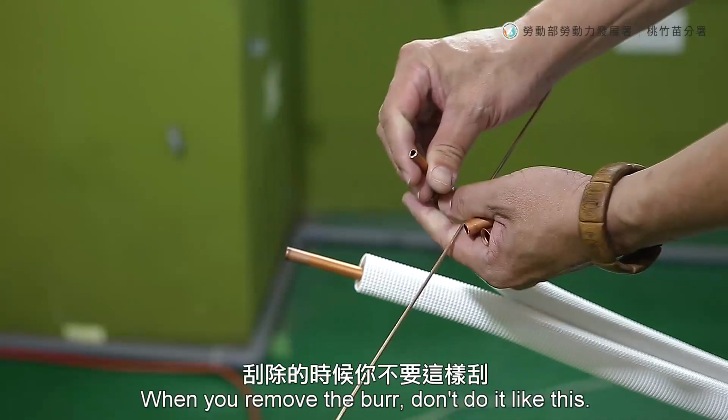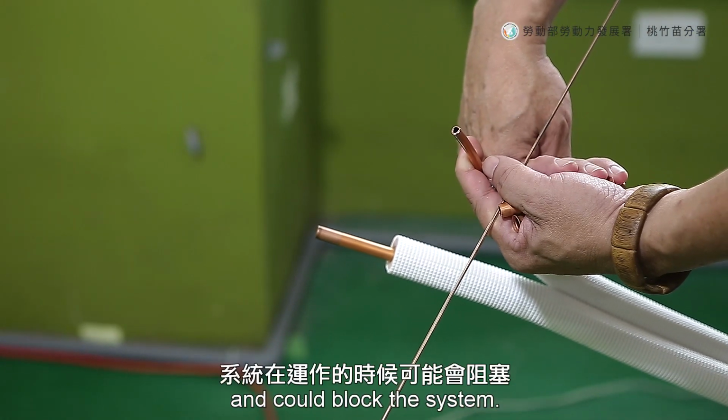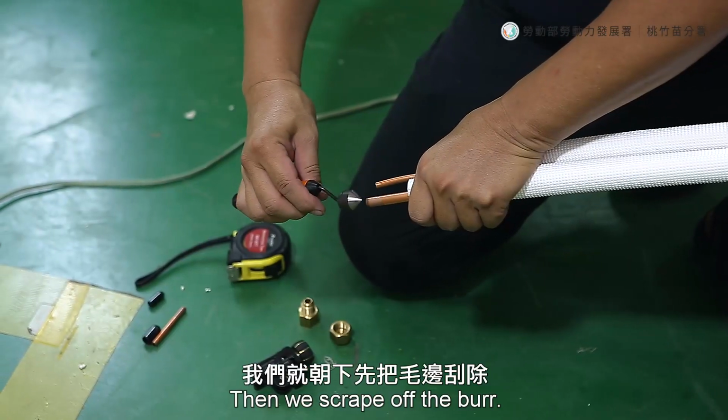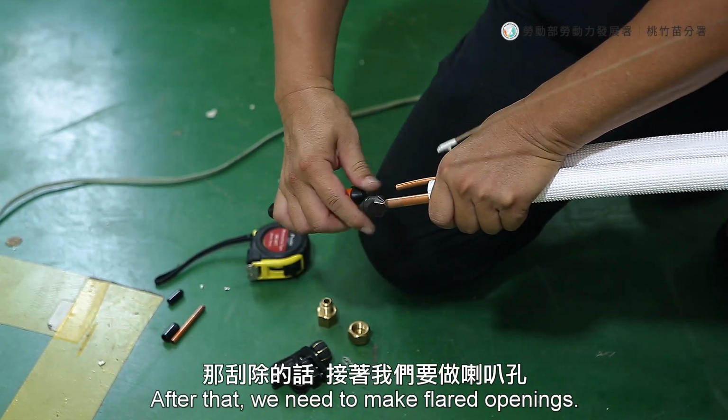When you remove the burr, don't do it like this. If you do it like this, copper shavings might get inside the pipe and could block the system. When scraping off the burr, make sure it's facing down. Then we scrape off the burr. After that, we need to make the flare openings.